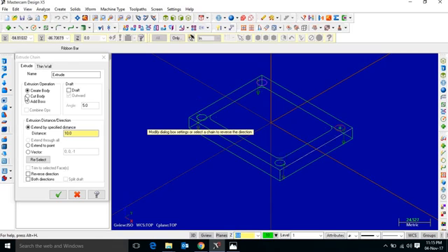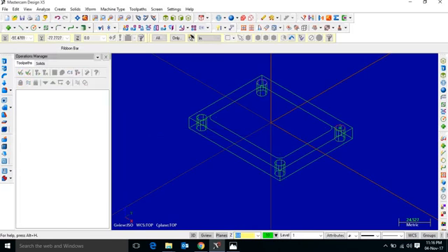Now they are okay. So we have to cut the drill, cut hole. So select the cut body, extended through hole, right? We have to extend the drill throughout, so extend through hole. Or if you know the dimension of the cutting, select this option, extended by the specified distance, and put 10 mm. Okay, so now here we have to extend it through, so extend through. Okay, now they are drilled.